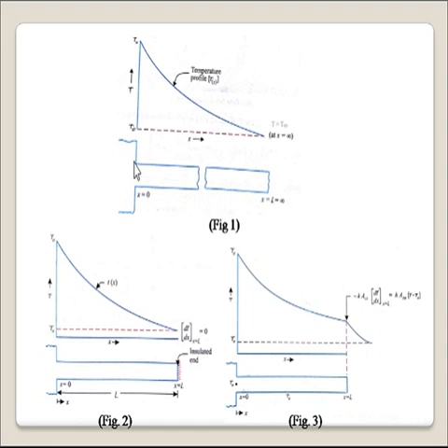Heat from the base will be conducted into the fin along the length, and it goes on decreasing from base temperature to surrounding temperature. So in an infinitely long fin, the temperature of the tip becomes equal to the surrounding temperature, and this is the typical temperature profile for an infinitely long fin.